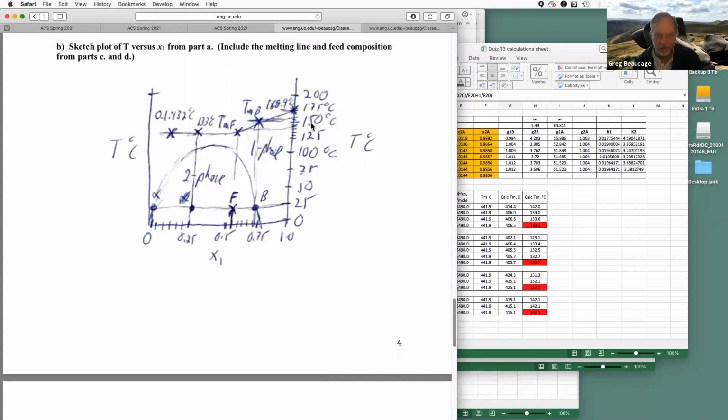But it's 100% paracetamol. That's the paracetamol melting point, and then it just drops. So you end up with this big gap, right? There's a huge temperature jump, like 100 degrees. So it's kind of likely that even at the feed, there's a big driving force for crystallization, probably more than for phase separation. So even the feed probably would crystallize before you ever phase separated beta. And that could be a problem.